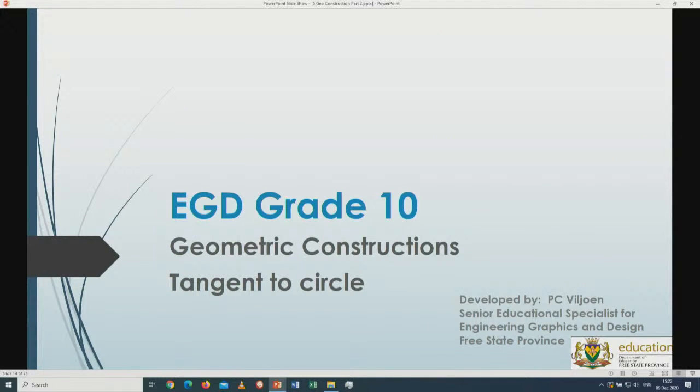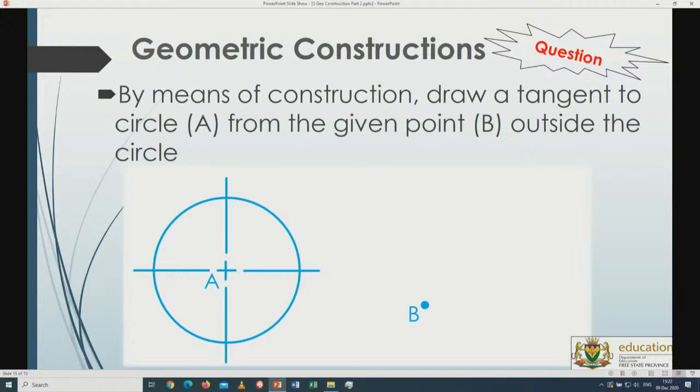All right, geometrical construction on tangent to a circle. Now, what is a tangent? A tangent is basically a line that will touch this circle only at a very small portion over here. Now I have to draw a tangent line from out here outwards. Sometimes you can say for yourself, it's quite simple. Just take your ruler and take it from B outwards, and then if it's just intersecting with that point, you simply draw the line.